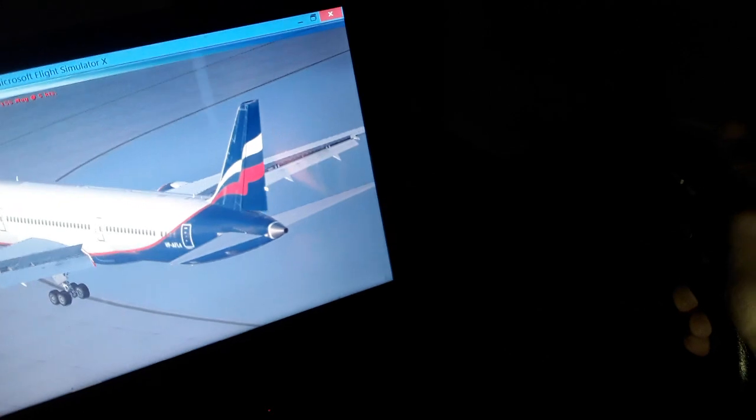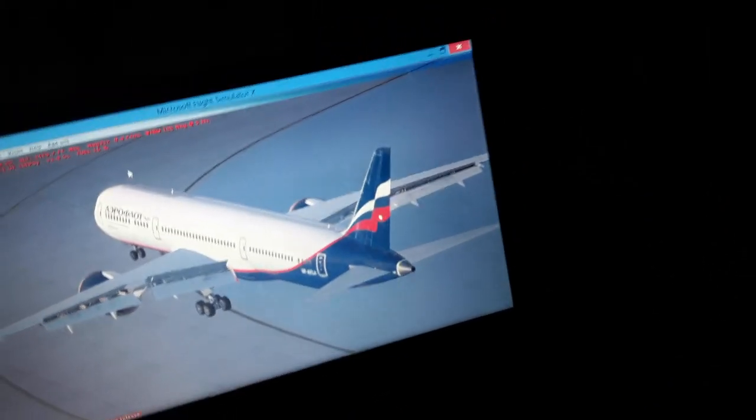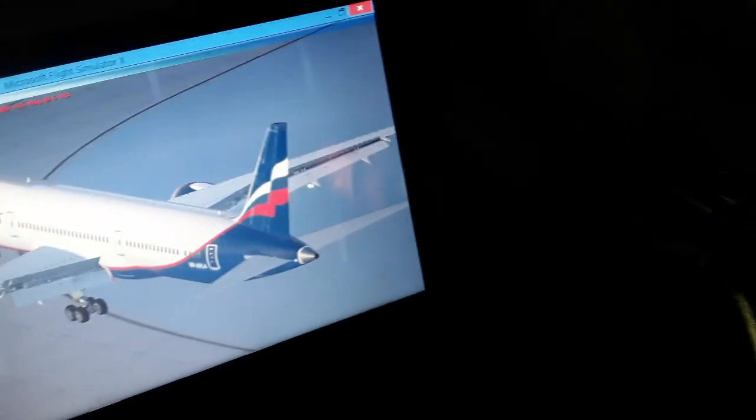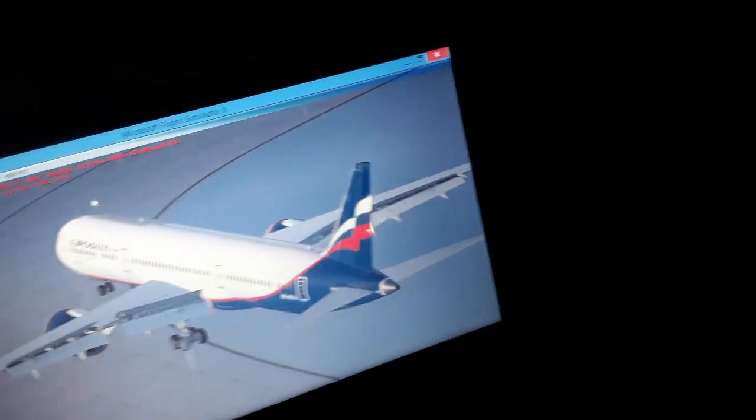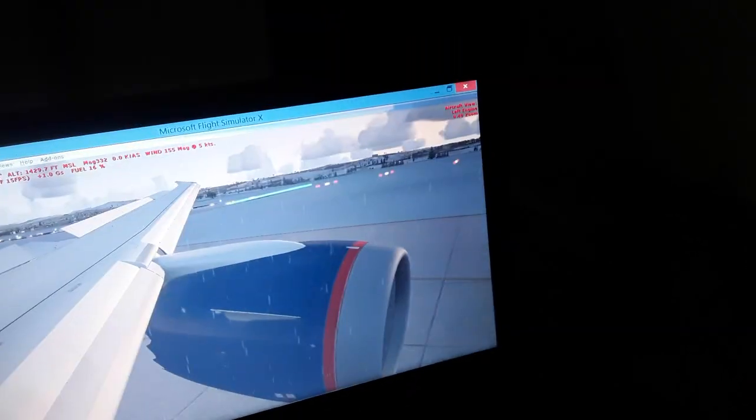It's also the yawing axis of the aircraft, where the nose wheel, the forward nose wheel, and the rudder are used, the vertical stabilizer, to maneuver the aircraft either in the ground or in the air as we take off, or in the air as we fly. So the yawing axis is also the rudder pedals use axis. The side stick I have here is the left and the right rudder pedal movement, as you can see. So these are the rudder pedals that use the rudder. As you can see, rudder pedals, left rudder, right rudder.